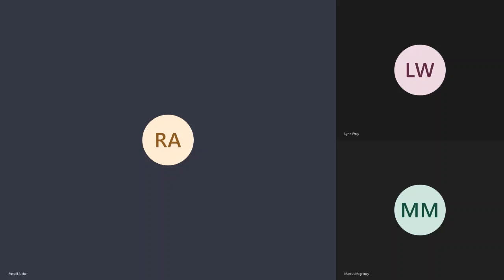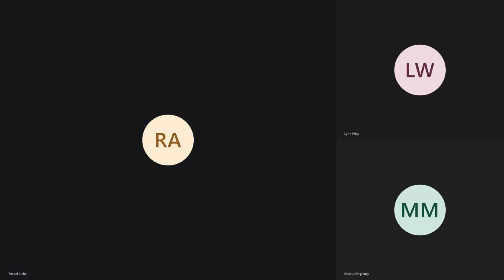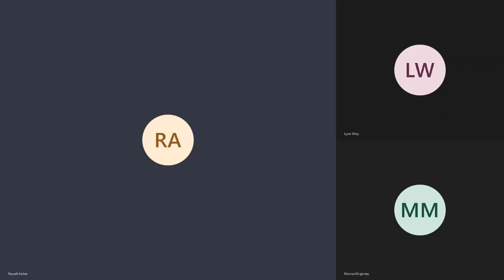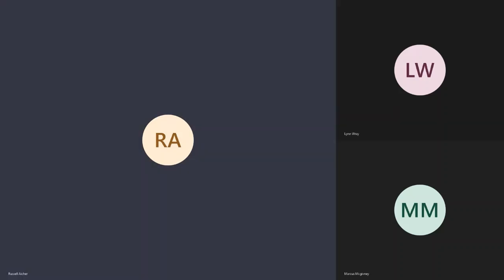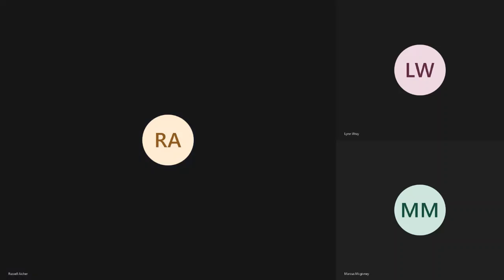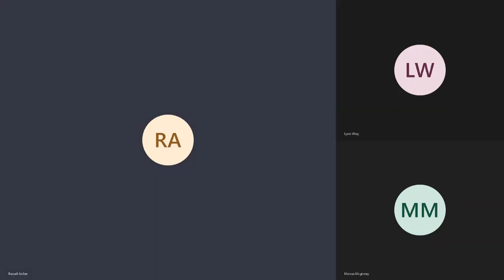For the roads, I would digitize the center lines as a separate shape file, and then I would buffer them to, like, I don't know, what's our buffer? Our roads are probably 26 feet across, so 13 feet. And then you have a polygon. You could do an erase with your road buffers on top of everything else or whatever, and then sort of do a merge.